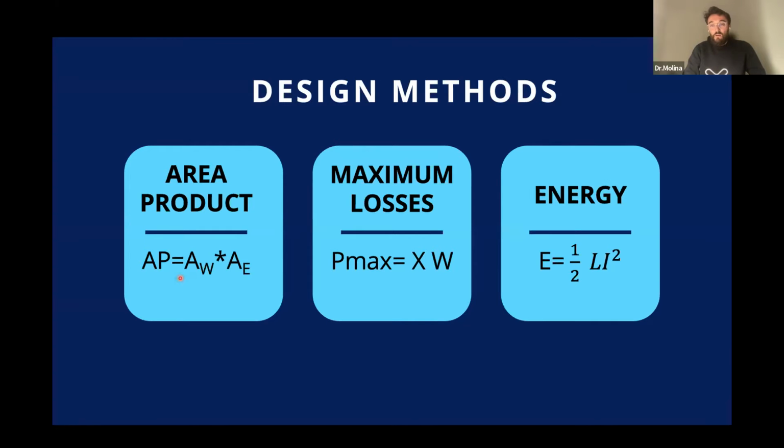It's the first method I read in my life. It was in the Inductor books, and basically consists of defining, I mean, doing the design in the reverse way. You define which are the maximum losses you want to have in your component, and then you would start doing the calculations in the reverse way. Even in the Inductor book, they define the maximum temperature at the beginning. It's like the maximum delta temperature they want to have, and then they go in that direction.